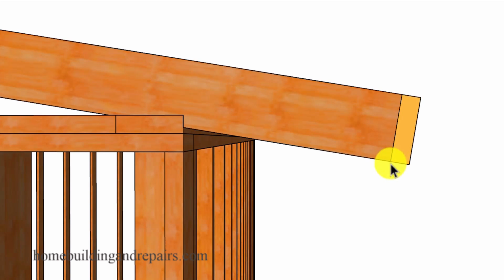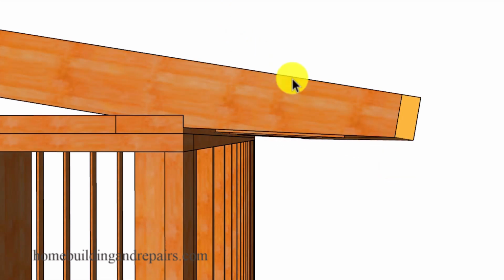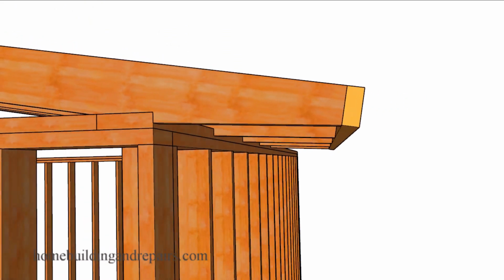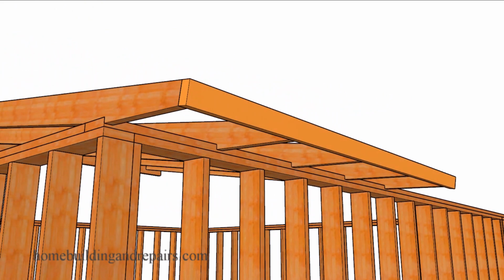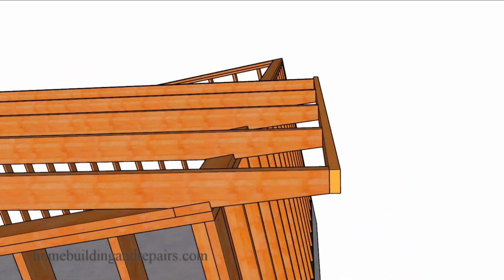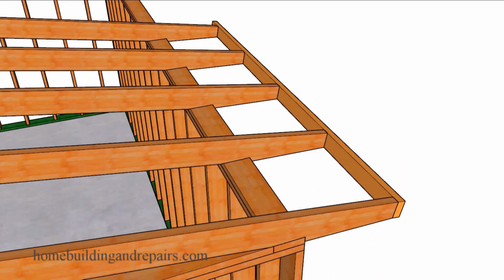That usually doesn't look very good. And of course, if I want to use a 2x4, I can simply shape the bottom of the roof rafter. And that can be done a variety of different ways. And this would be one of them, simply going from this point here to this point here, or a 3.5 inch measurement this way, and then going to the bottom of the roof rafter seat cut. And you can get as creative as you want to. The only thing I don't recommend doing is making this smaller than 3.5 inches.